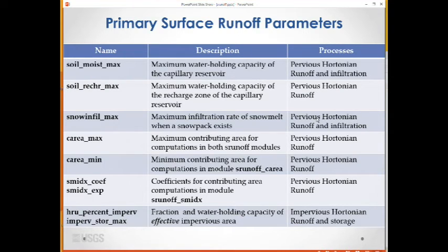of streamflow. If the simulated streamflow is much flashier than observed, it may be necessary to reduce the impervious fraction. If the simulated ET is higher than expected, it could be that the specified impervious fraction and/or impervious water holding capacity are too large, as water on impervious surfaces evaporates at the potential ET rate. A great deal of attention and analysis may be needed to estimate impervious parameter values.